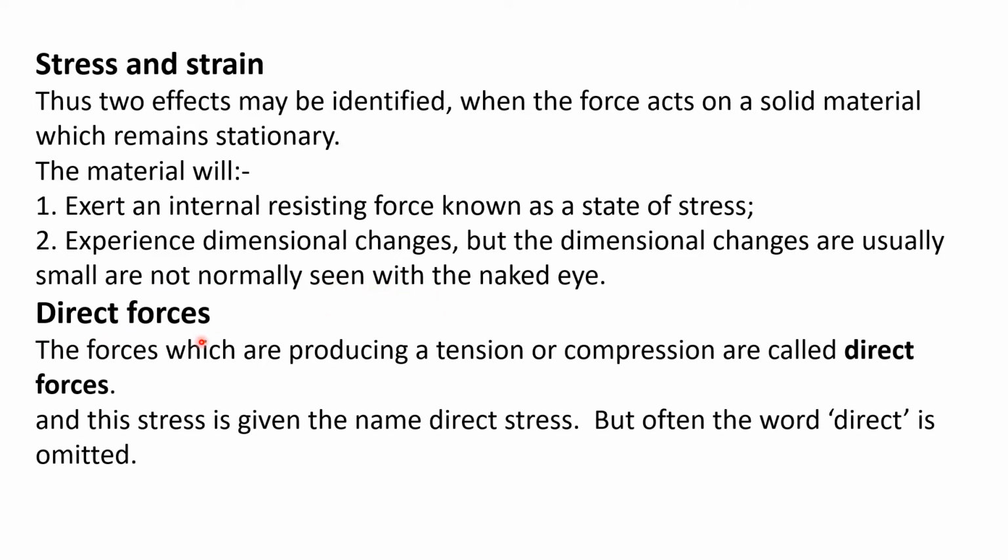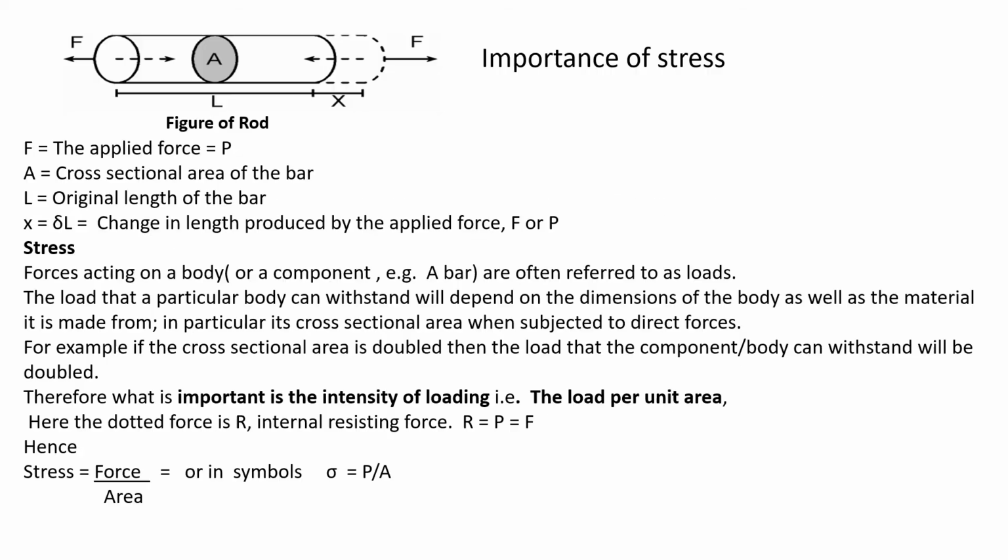Then the forces which are producing tension or compression are called direct forces, and this stress is given the name direct stress, but often the word direct is omitted. So even though it is a direct stress, we call it only stress. Now here there is another figure.